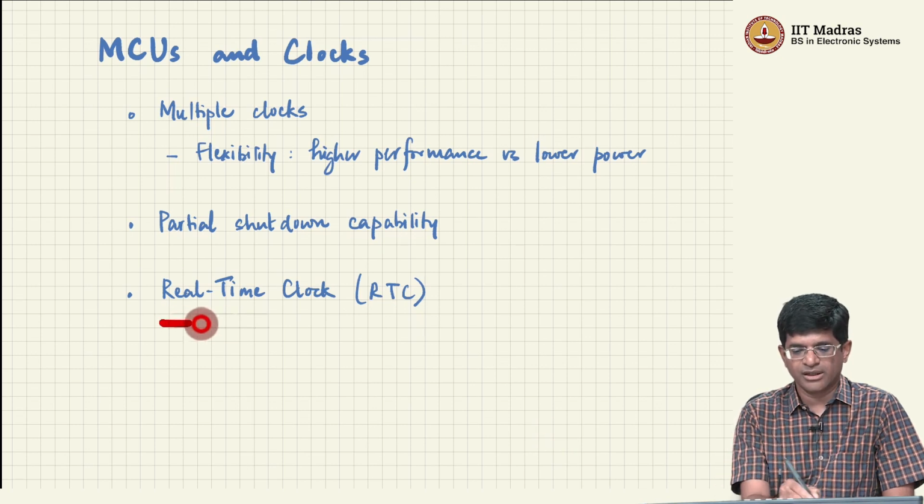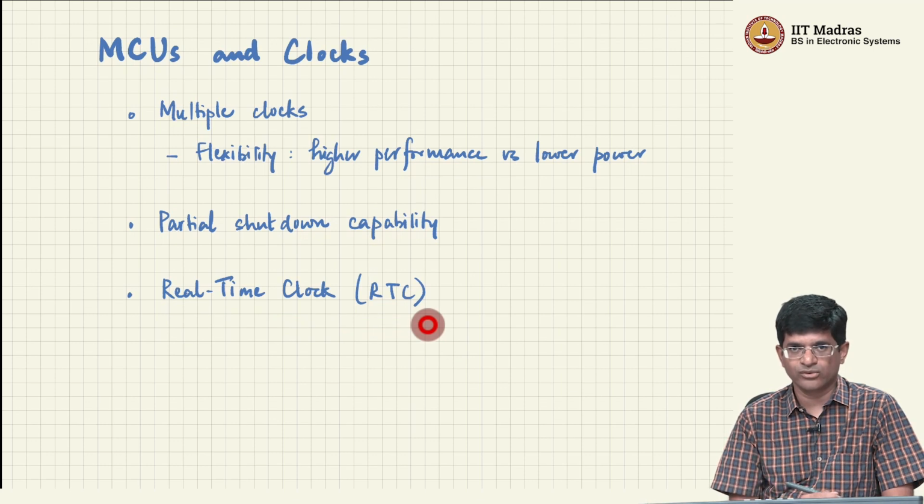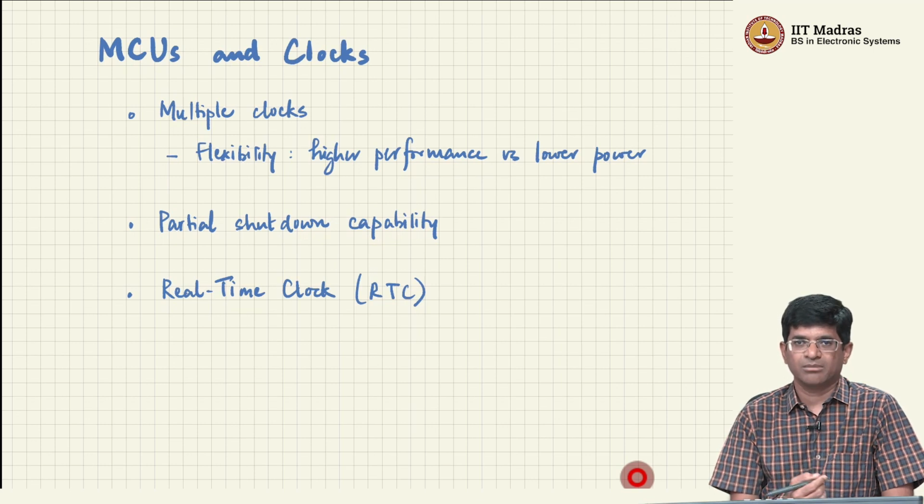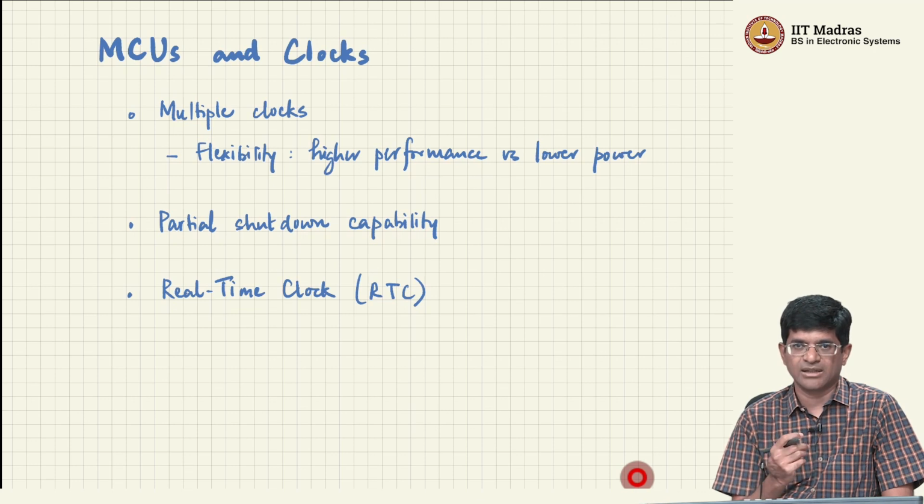There is also something else called a real-time clock, which has a number of other useful applications. In particular, there are applications where you can put pretty much the whole microcontroller to sleep, except for this one slow clock which is almost at the hertz level, right? It's operating at a very low frequency compared to what the microcontroller would normally work at. But it can instantaneously, or very quickly rather, wake up the entire microcontroller and get it back into a functional state.